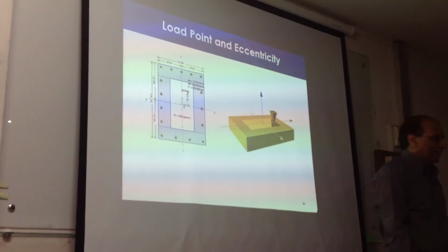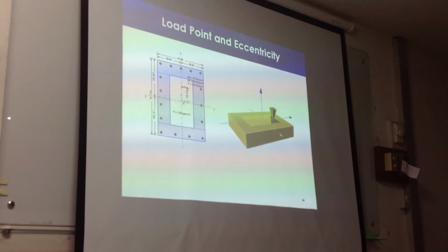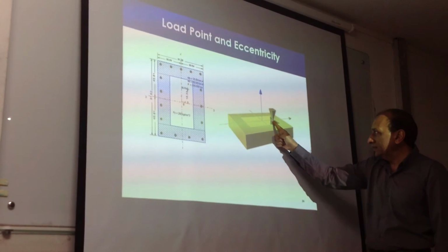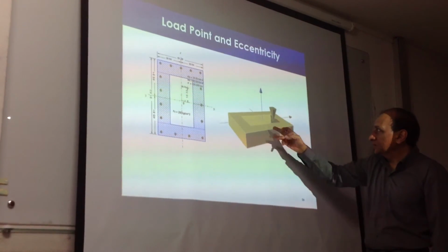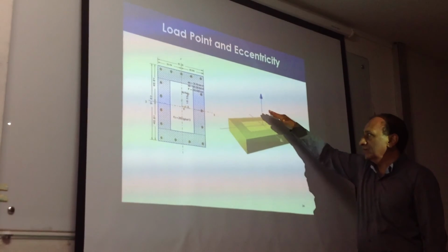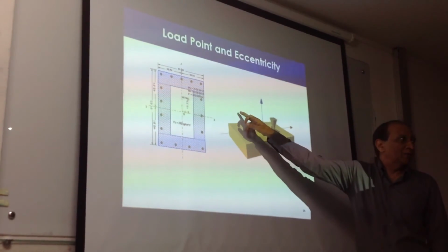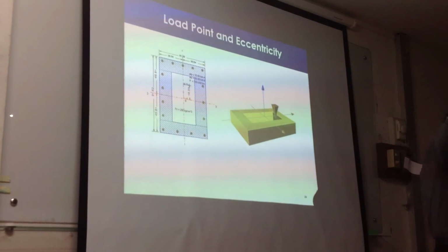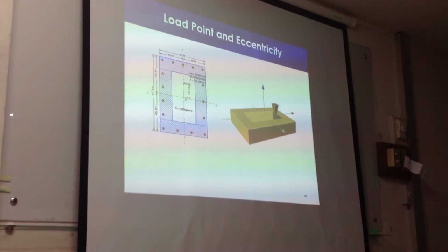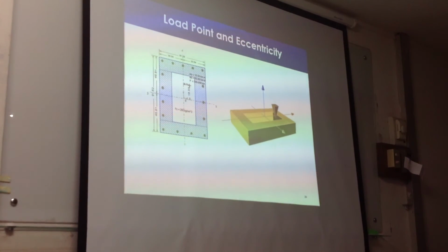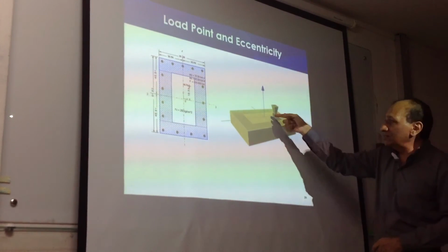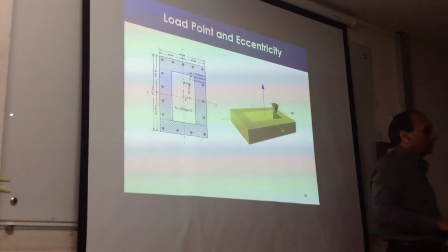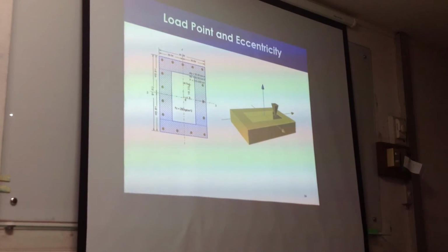around the cross section. And because of that shift, you can imagine the cross-section will deform perpendicular to this point. So if this point is here, the cross-section will deform like this. So it will move this way, this side will come up, this side will go down. There will be compression here, tension on that side. Correct? So that means this load gives you the idea that if you move around, the cross-section will keep on doing like this, right? Depending upon where the load is moving. So every time the moment is changing, the cross-section will bend to conform to that location of the load, right?